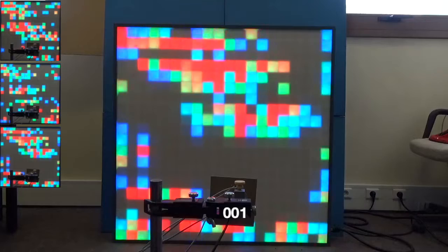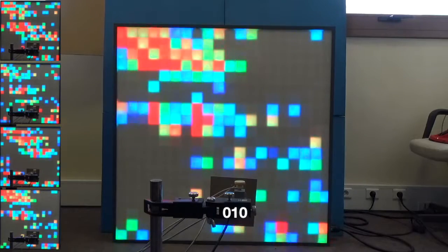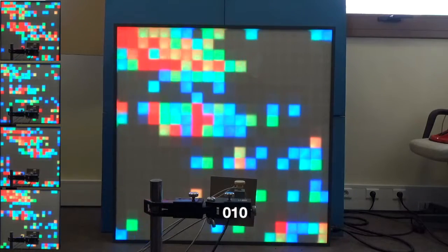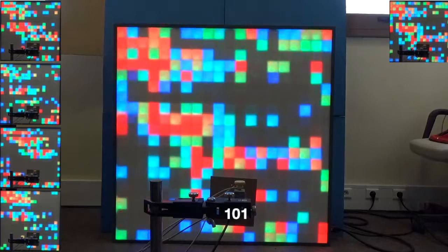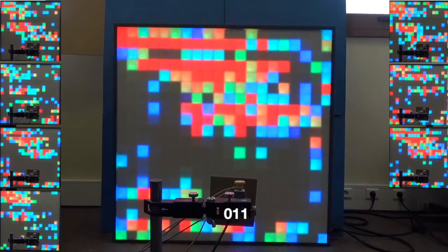Each time we change the coding bits to transmit, we can see that we obtain a new radiation pattern that corresponds to a specific signature. The signature will be used by the receiver to retrieve the initial information, that is the 3 spatial modulation bits. These signatures are very different from each other, and it's quite easy to discriminate between them at the receiver side by applying simple correlations between learned patterns and received ones.